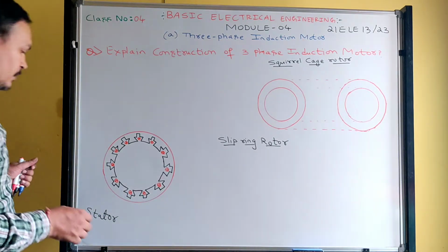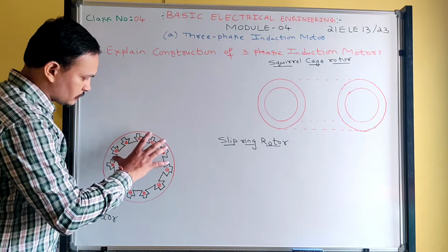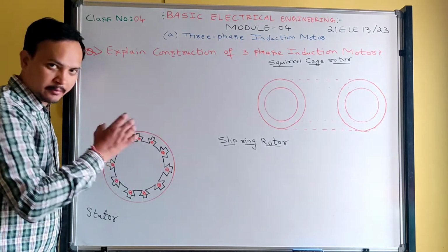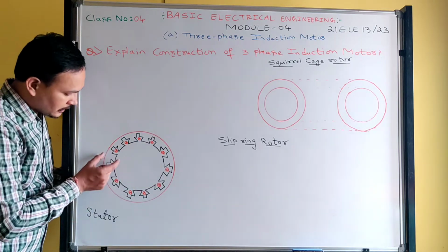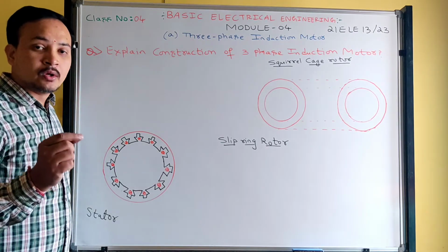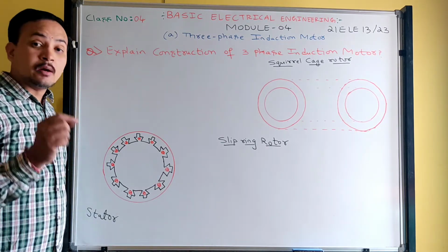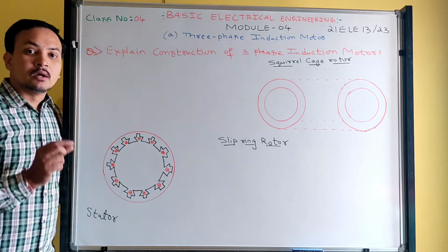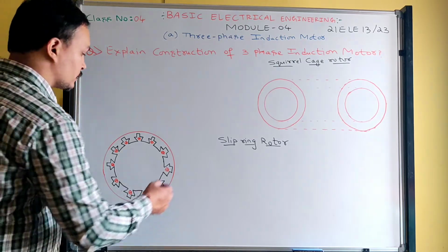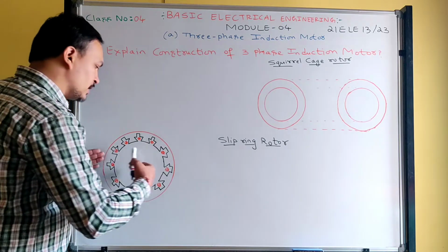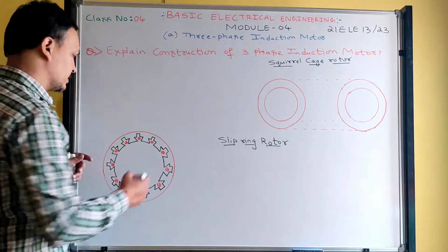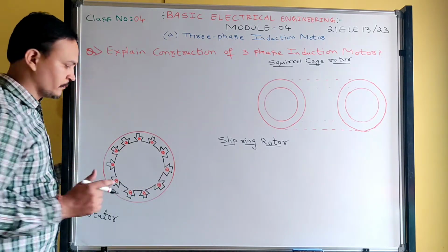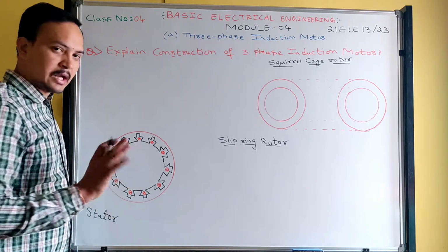See now, let's list out the parts. See guys, look at here. So this is called a stator laminated plate. Got it? The thickness of this plate varies from 0.25 mm to 0.5 mm. So that will be the thickness of the stator core. Like that they are joining n number of laminations side by side. For example, we can write a diagram like this. You must write only this much. So what I am writing now, you need not write. Just understand.